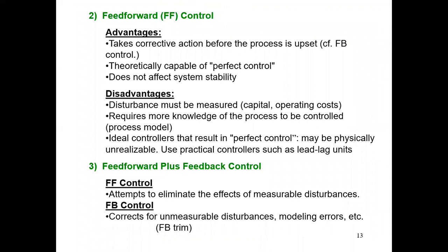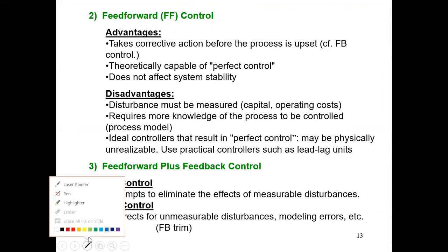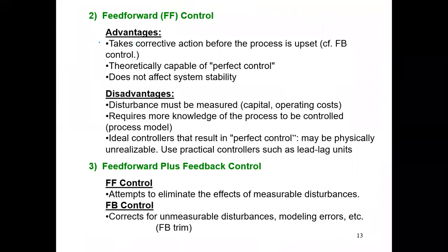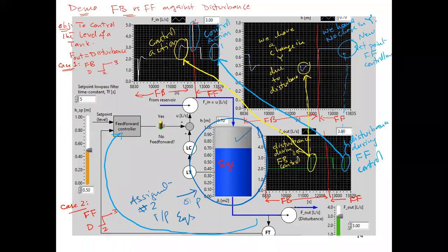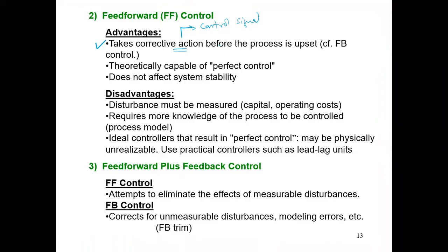Now, what are the benefits of feed forward control? What we have seen is that it was able to take the actions. One advantage is that the corrective action, which means the control signal, was taken by the feed forward controller before the process was upset.